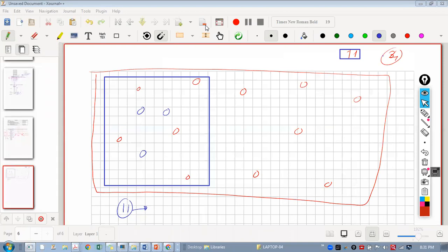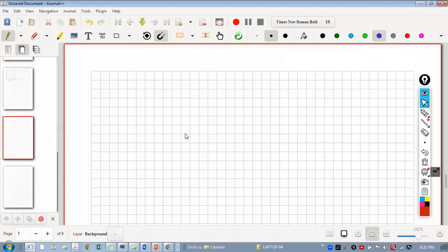Sir, if footings are resting on hard rock, black basalt or compact basalt, how much capacity can we take without doing any exploration? Without any exploration. Okay. Yeah, this is hard rock, unjointed. See, I will tell you, for unjointed compact basalt, I have even taken the capacity this much also. 250 tons, yes, 250 tons also we have taken.